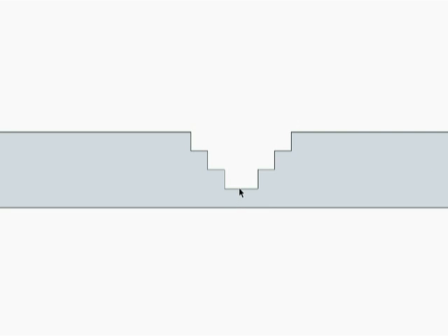Well, the first pass is this center pass right here, and it made it at a 75% depth. And then I spaced the next lines, all the lines are spaced 1/16 inch apart. And that yields, you know, half of the bit diameter, basically. So now I've got the bit coming in and cutting 50% depths, and then finally 75% depths.